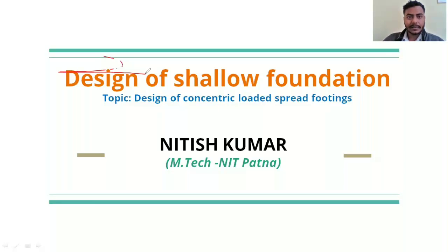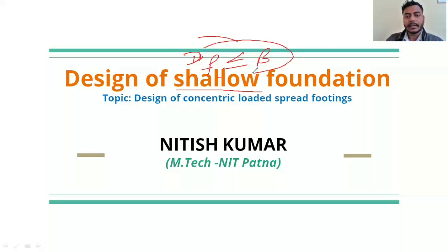So we have seen that shallow foundation, basically we know that when the depth of foundation is less than or equal to the width of foundation, that is called a shallow foundation. So there are different types of shallow foundation. In the first lecture I have discussed the strip footing. In this lecture I'm going to discuss split footing or isolated footing. So we are going to design a concentric load split footing.